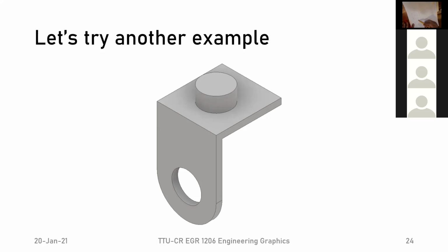Now, this is a cylinder, right? It looks like a box to us or a rectangle, but it's actually a cylinder. So we have to make sure that people know that. So we'll add a center line here too. We'll do a shorter dash in the middle and then a longer dash along here. So these ones, let's extend these a little more. I probably should have made this one a little shorter to make it clear.